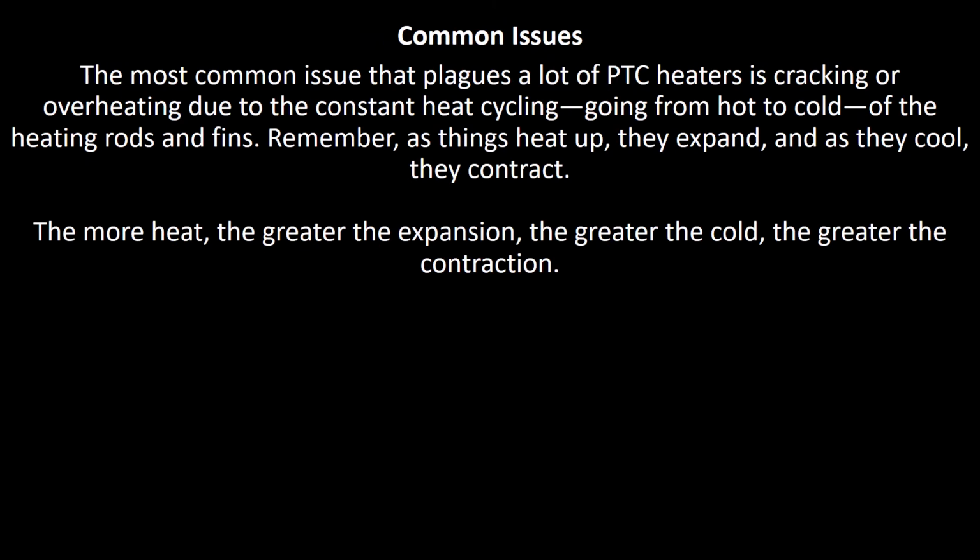What are common issues with this system? The most common issue that plagues a lot of PTC heaters is cracking or overheating due to the constant heat cycling, going from hot to cold, of the heating rods and the fins. Remember, as things heat up, they expand, and as they cool, they contract. The more heat energy, the greater the expansion. The greater the cold, the greater the contraction.